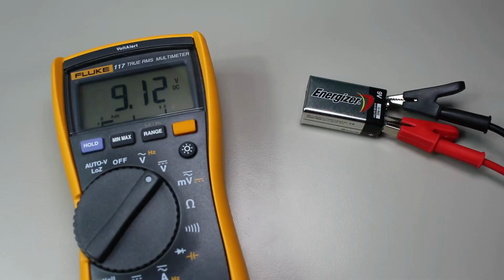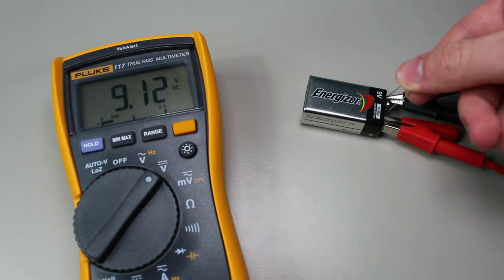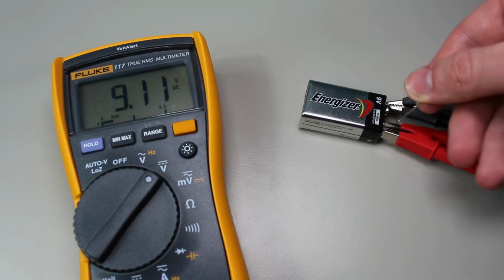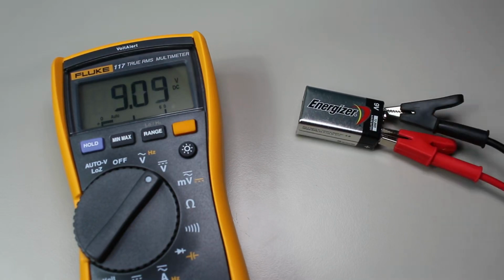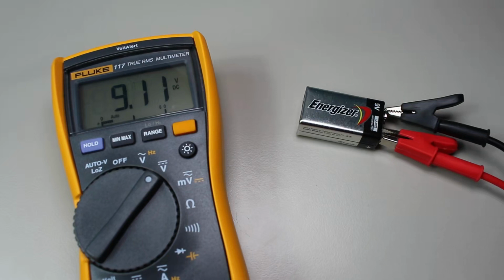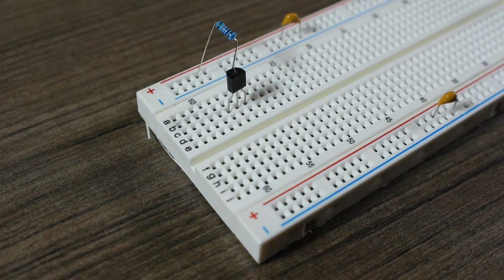A battery is a great example of a voltage source, since it maintains its voltage despite changes in the load. So, just remember that a transistor will do its absolute best to maintain a constant collector current flow, and it will drop a varying voltage across the collector emitter path just to keep that same current flowing.